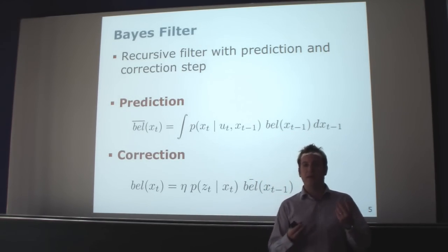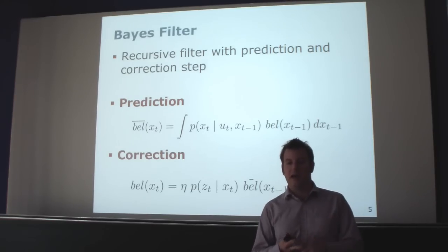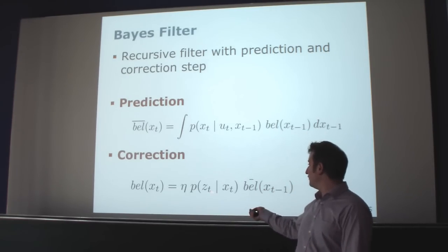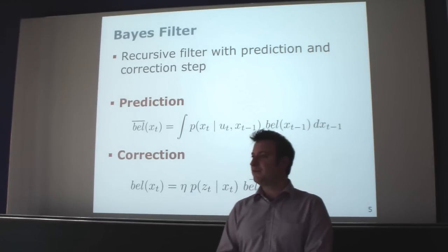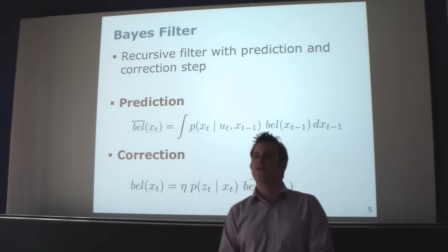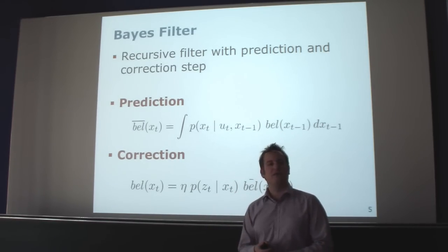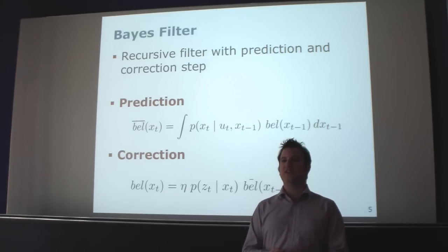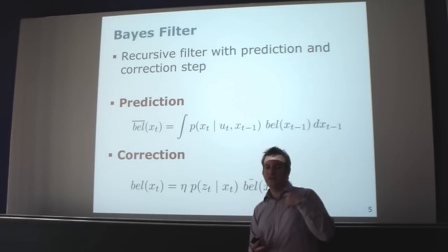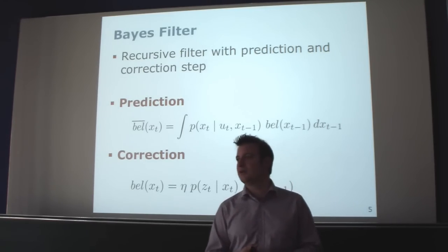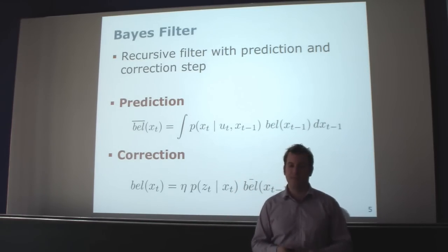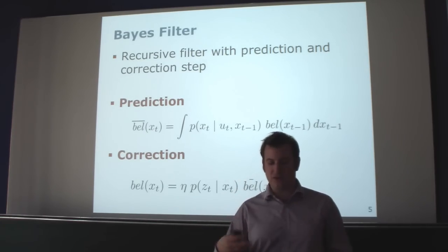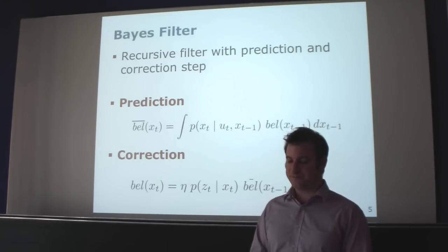And in the extended Kalman filter, all of those beliefs here are Gaussian distributions. So they're all Gaussian, that's an important thing. And the second thing is the Kalman filter, just to remind you of that, assumed a linear model. In reality, the world is typically non-linear, so what the extended Kalman filter was doing, it was using a first-order Taylor expansion, approximating the nonlinear function by a linear function, and using this approximation to do the estimation.